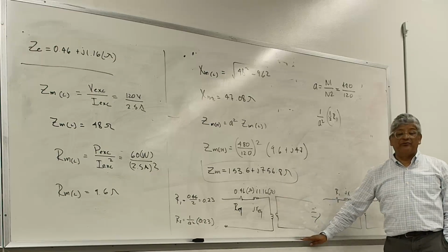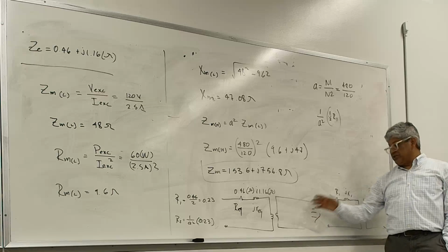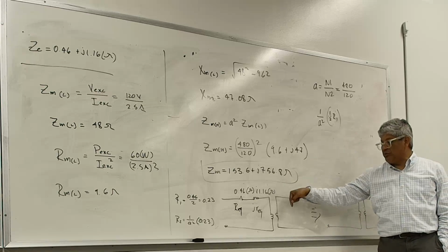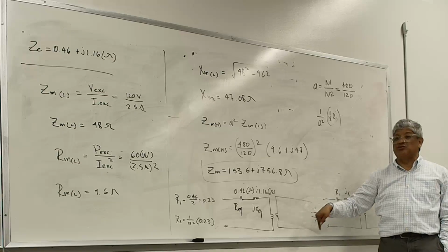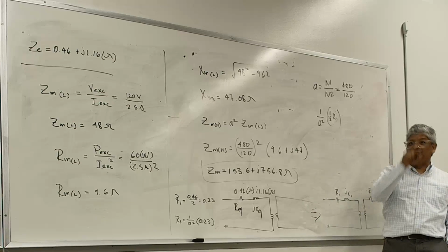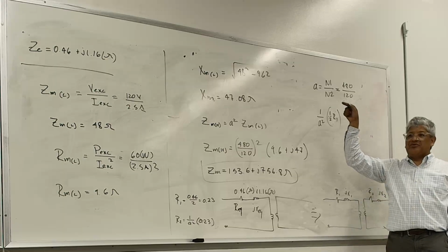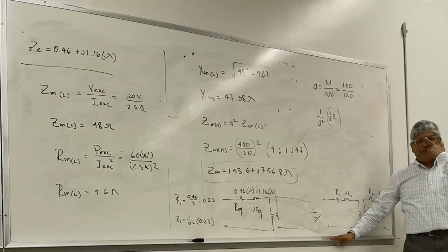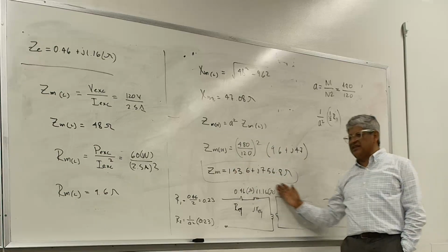It can confuse relays, because there is no load, but when you close it there's a current with a high content of harmonics. When you start to shape that hysteresis, you take the transformer into the saturation point, and sometimes relays get confused and trip. That's mostly for protection engineers, who want to know what this excitation current is.